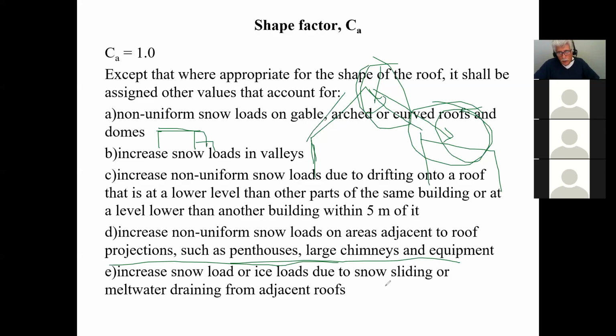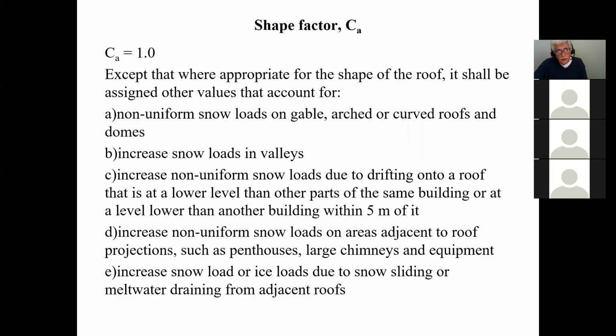So this one is for when the roof has a slope and there's another building next to it, and the snow can slide off and accumulate onto the other roof. We will talk about this case especially, because I found that it has been very problematic in our practice. People don't realize it, it's overlooked, and it always causes problems. So I want you guys to be aware of it.